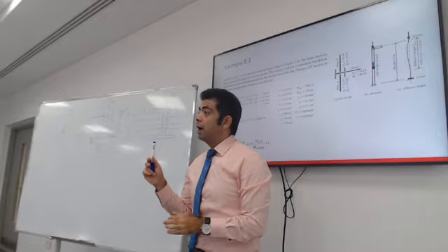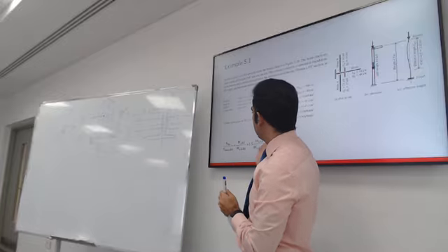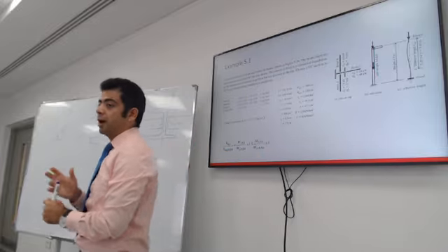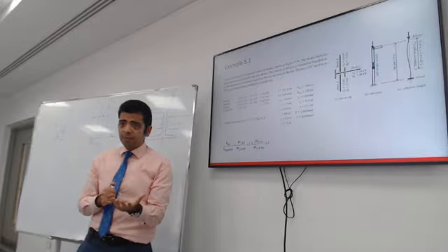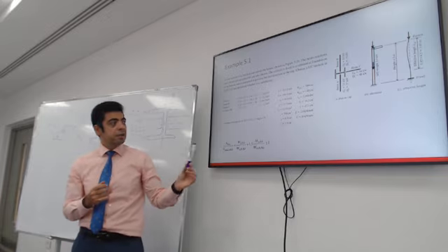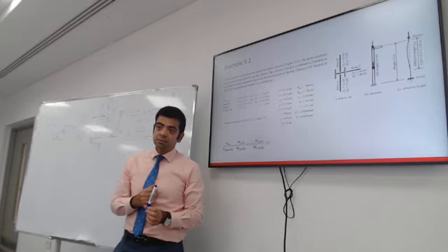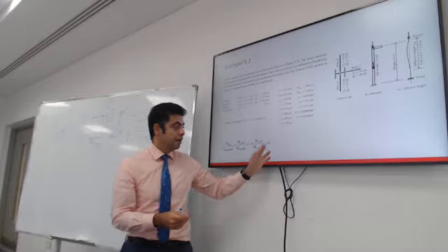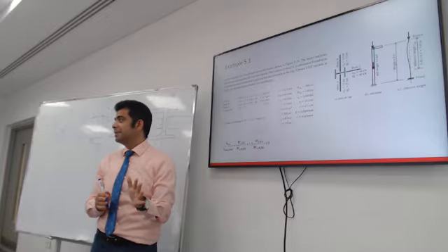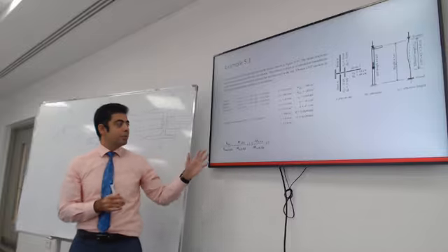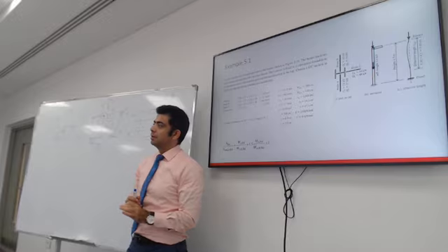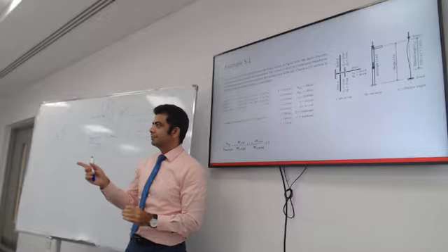So, if you choose a section and it turned out to be 0.5 when you add all the factors, is this an acceptable design, or do you need to change the section? It's acceptable. Why? Because it's less than 1. Any other thoughts? Maybe we can find a more efficient or more economic section.